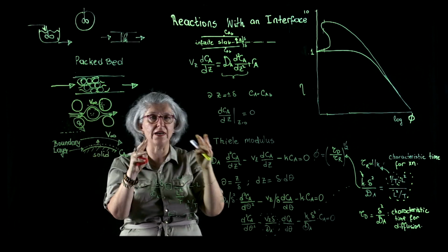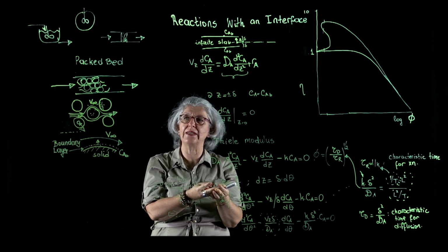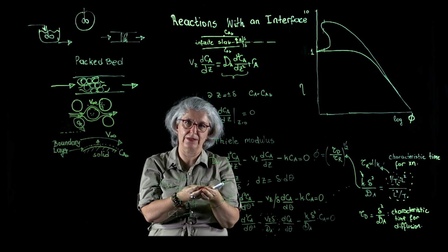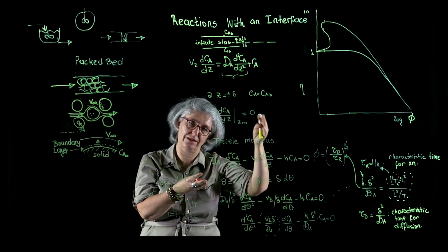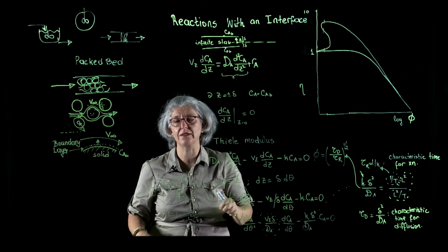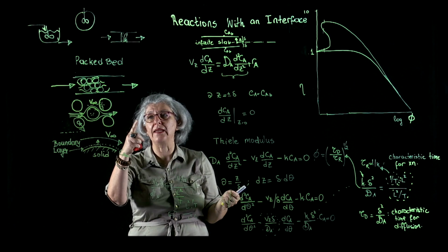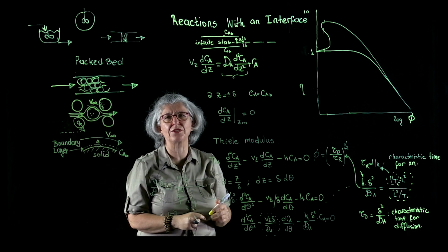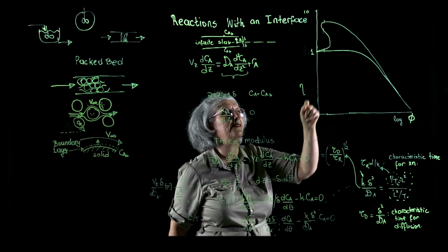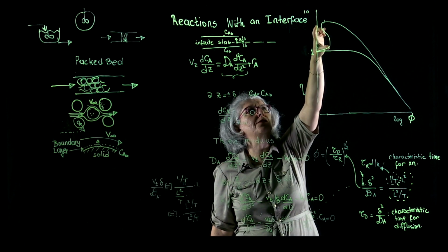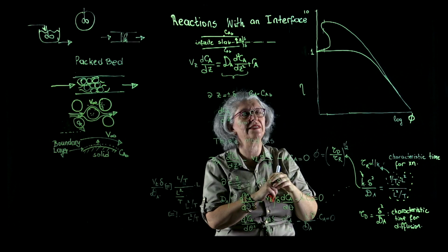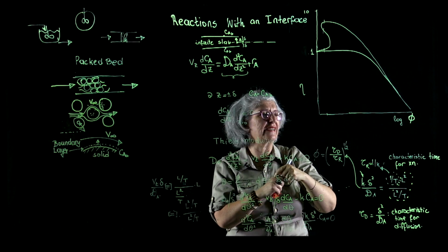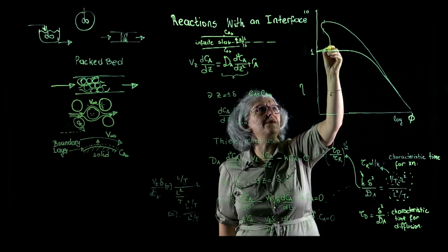So the multiplicity of these effectiveness factors are due to different zones of temperature in the catalyst particle. Outside the surface, the temperature is equilibrated, the system is thermally equilibrated with the environment. In the middle of the catalyst, we have very high temperatures, all right, and then we have strange behaviors of effectiveness factors increasing with decreasing Thiele parameter.